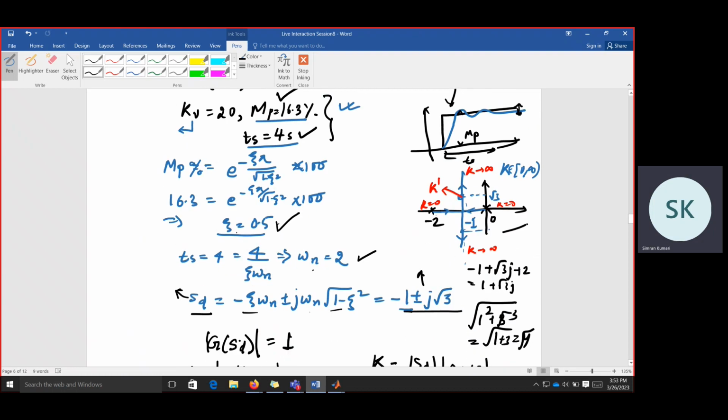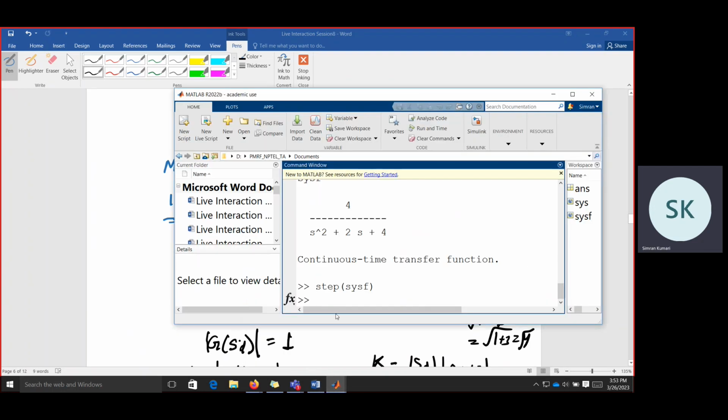If we see the root locus, we have two poles, at 0 and -2. At gain equal to 0, the poles are at these locations, which is the open loop system, and as the gain tends to infinity, the root locus looks like this. So the poles move like this. We can see this point is -1 on the real axis, and now for j root 3, as the gain is increased, it covers all the imaginary values. That means this lies on the root locus. And we had seen this from the root locus plot in MATLAB also.